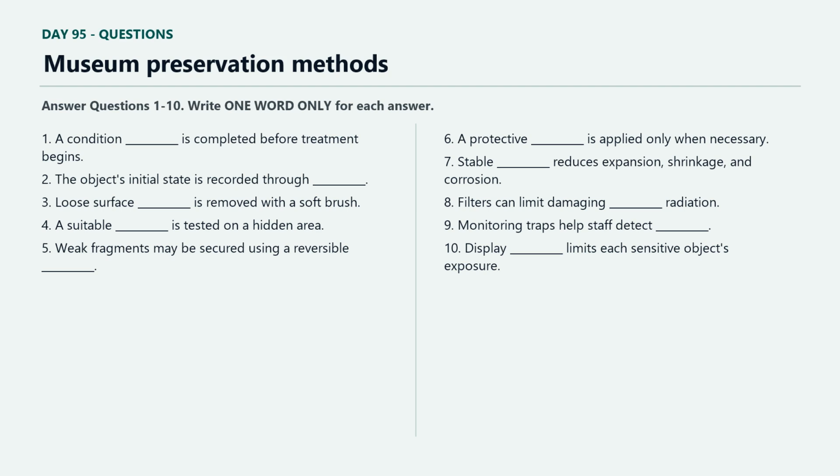Temperature is commonly measured, but many museum materials respond particularly strongly to the amount of moisture in the air. Wood, paper, leather, and textiles absorb and release moisture as surrounding conditions change. Stable humidity therefore reduces repeated expansion and shrinkage, while also limiting corrosion and biological growth. Stability is often more important than attempting to maintain one perfect number in every room. Rapid fluctuations can place stress on join materials because each component may react at a different rate.